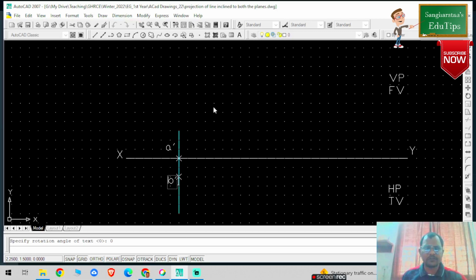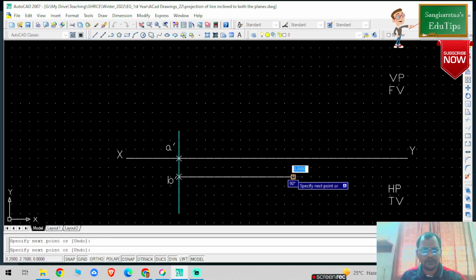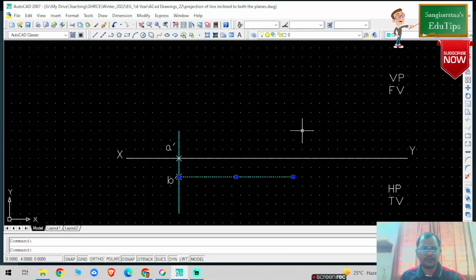Immediately what you need to do is draw one projection line. If you are drawing on the XY line, it should be visible, or it may not, right? So what you can do is draw from this particular point B. I am drawing one projection line here perpendicular to this one. If I draw here, it will not be visible, so no issues. This will work as a projection line. So convert this particular line into cyan color.